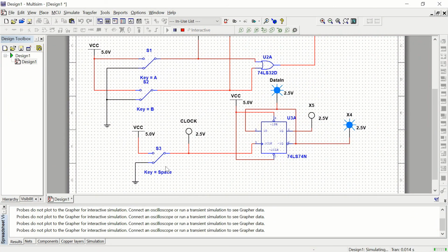So everything started out low. Okay, it took a second for that to catch up. So we have a low clock pulse. So this is sitting at 0. And this not Q is sitting high and Q is sitting low. People that had taken that dual enrollment class will know what that symbol means. Not Q and then Q. So let's flip the switch. Okay, and what that did was it basically flipped the outputs. So now this one is high and this one is low.